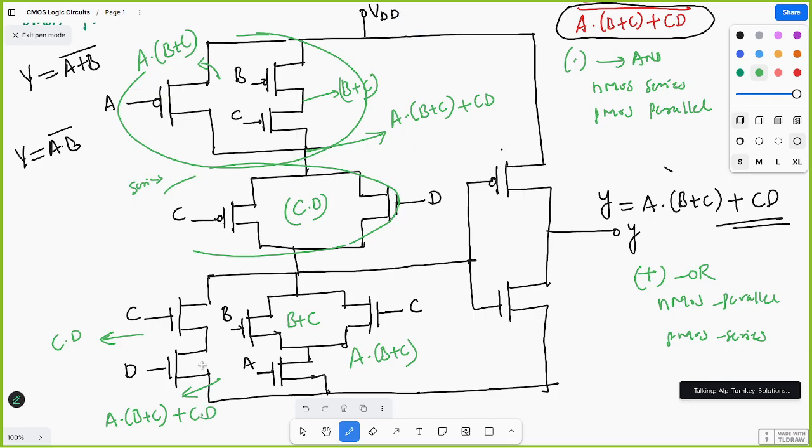Okay, but here the expression you have given is in true form. When we implement CMOS, we implement it directly for NOR gate and NAND gate. That means this is the complemented form, it is given, we can implement. But how to implement this? We know from De Morgan's law, the inverter law, A bar whole bar equals what? A, no?